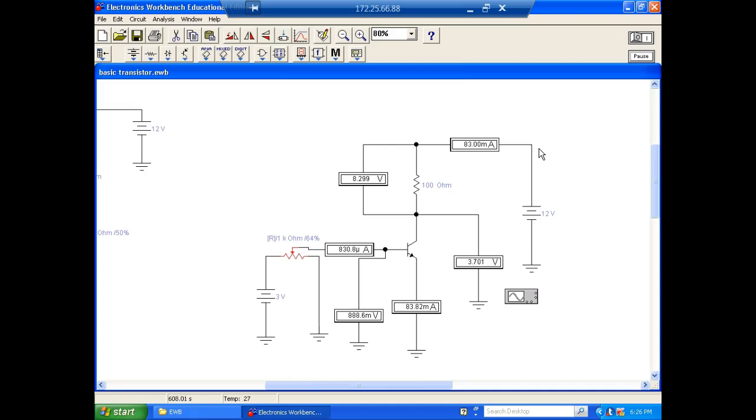These small signal transistors have a really good current gain on them. So okay, ain't that neat? And this is a simulation. We'll hook these things up and see. The transistor that we're going to use has a gain of about 100. It's the 2N3904, the NPN we're going to use. And it's got a typical beta, current gain, of around 100.